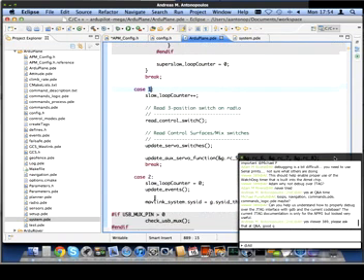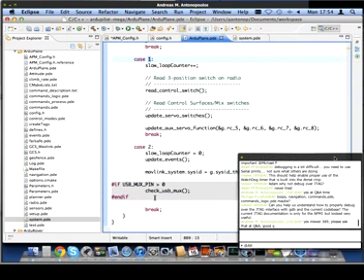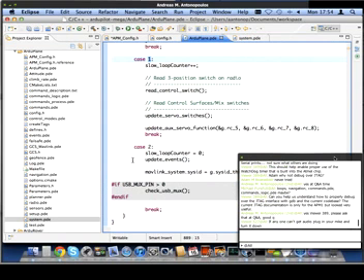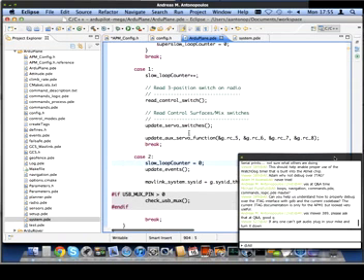And the slow loop uses the same little switch statement trick to scale down 10 hertz down to 3 1/3 hertz. It does that by dividing it by 3, case 0, 1, and 2. And that gives us a 3 1/3 hertz call. And we do things like read the control switch from the radio. That means that when you flick modes, it won't change modes in the plane at better than 3 1/3 hertz. So you'll get approximately 1/3 of a second delay when you switch modes before it actually takes effect.